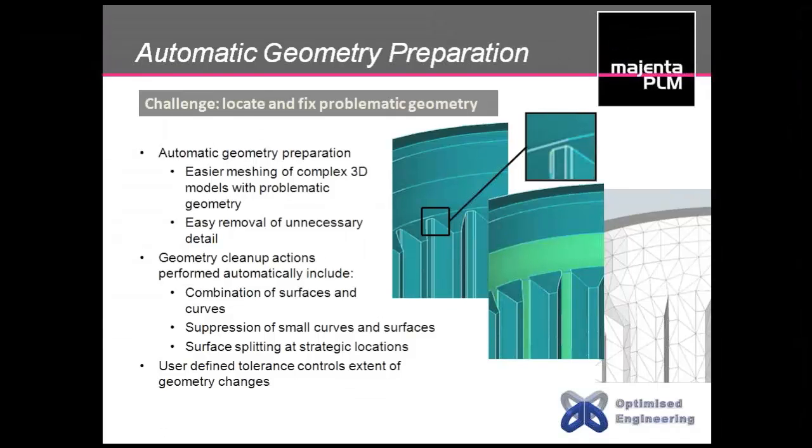But very often, Femap is used as a downstream application for using CAD geometry that's been developed by another engineer or even another organization. So the geometry may not necessarily be coming in at a quality that's suitable for analysis. But Femap gives a toolbox which allows geometry to be cleaned up and small features to be removed, patched together, etc.